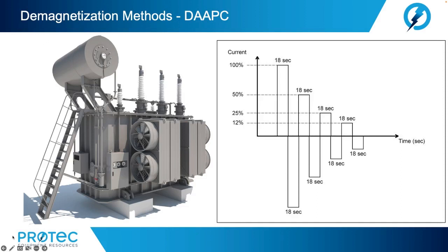The value of the initial amplitude is not important as long as saturation is reached on all three legs of the magnetic core. Following initial current charging and discharging, the next alteration is of 50% magnitude, and when reached, discharge is initiated, and the steps go on in succession until the very small value of ampere turns is applied at the very last step.